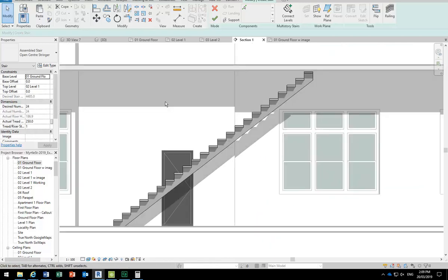So, do you think that'd be okay as a stair? It's 190, it's less than the 190 riser, so that complies. So why wouldn't it comply then? I'll give you a tip, it doesn't comply, so why is it still not okay? The riser height's okay, the tread's okay, the tread's 250. Exactly. You can only have 18 risers in a flight before you need a landing. So that's exactly right.